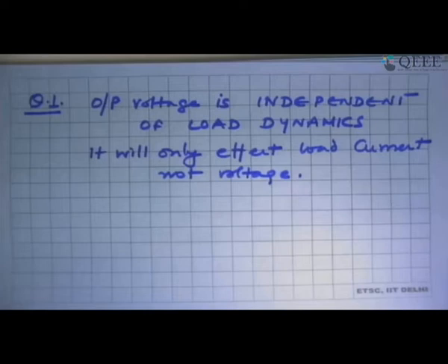Does a change in load change the voltage of the inverter? It will not. See, the output voltage is generated from a constant DC link voltage, so it is independent. If there is a change in any load dynamics, it will only affect the load current. Voltage will be rigid.